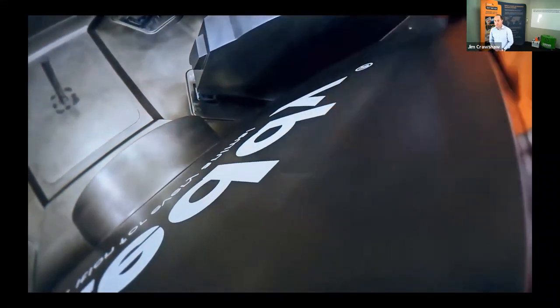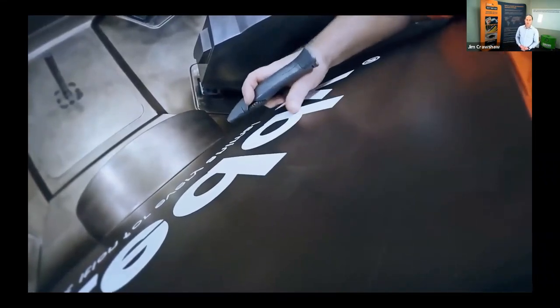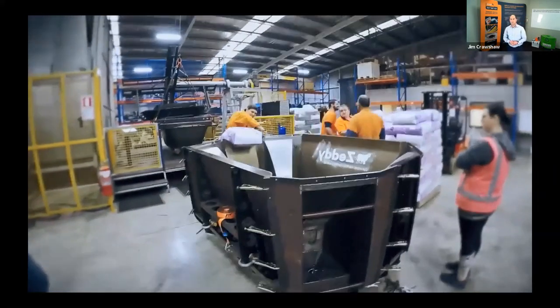Oh, here we go. Yeah, so what he's doing here is he's found a trapped air bubble. And when you find a trapped air bubble like that, it's best to lance it with a sharp knife and just expel the air like he's doing here with his thumb. If he had left that, that would have resulted in perhaps a small crater in the graphic.